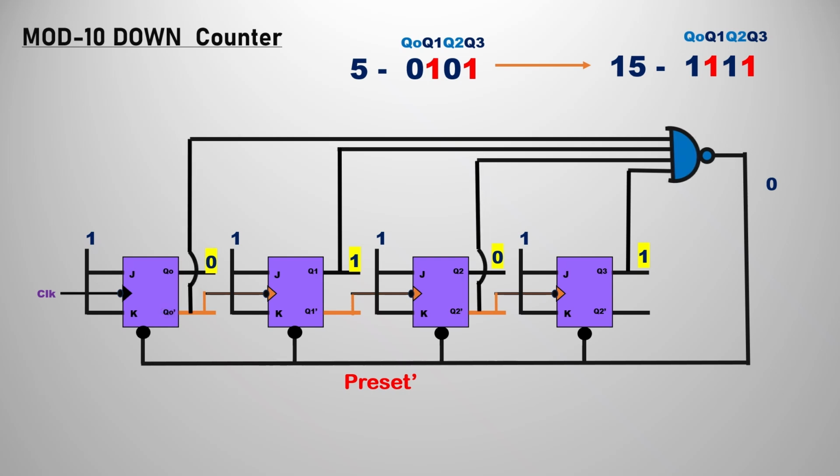Or if you don't want the NOT gates, you can simply connect with the bars also, because bars are readily available for us. So in the two cases, the q0 bar we can connect directly, and the q2 bar we can connect directly, as you are seeing there.